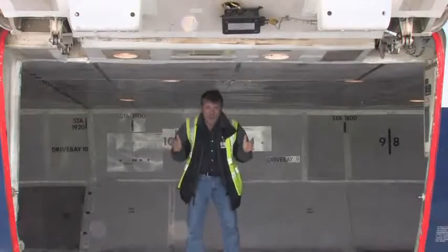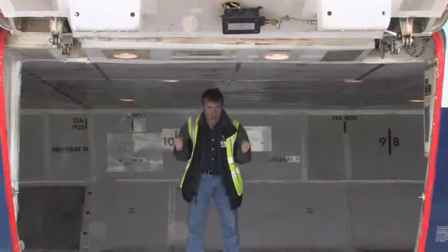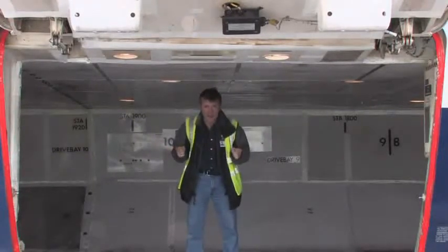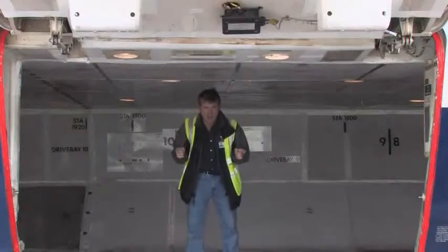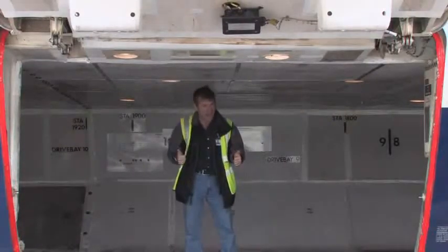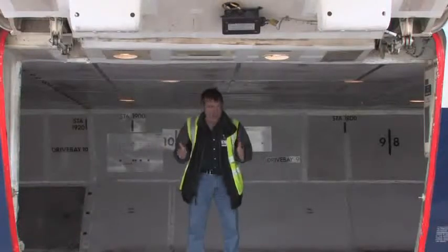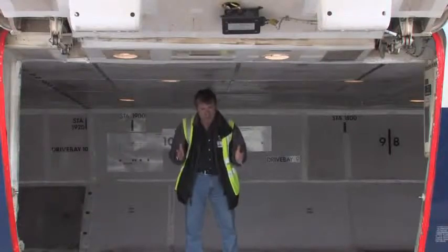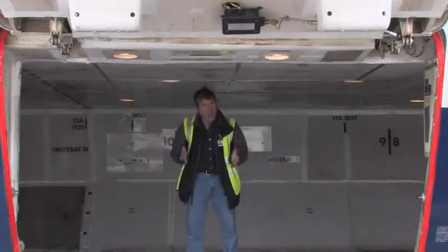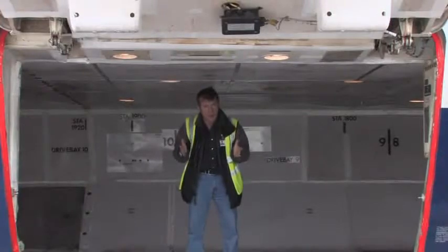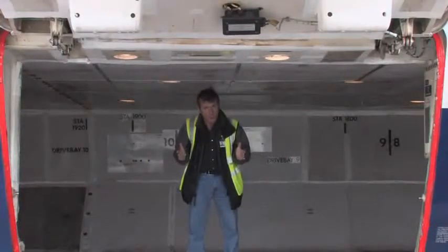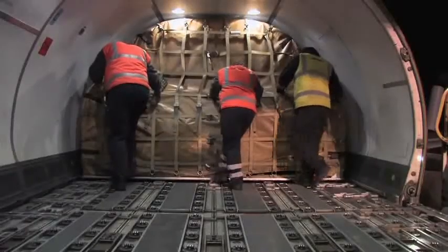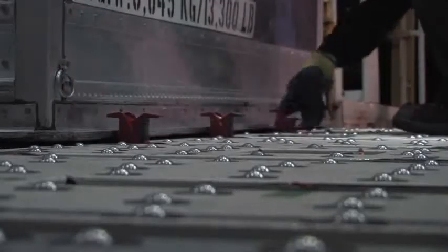Now, if the load is not adequately secured, strapped or locked, there could be trouble. Moving that around in here at 37,000 feet could damage the pressure hull of the aircraft. Definitely not recommended. Alternatively, moving a big load around in here can also change the centre of gravity of the aircraft, the C of G, and that could lead to control difficulties or even loss of control. So before you leave the hold, make sure that all loads have been secured, strapped and locked down.